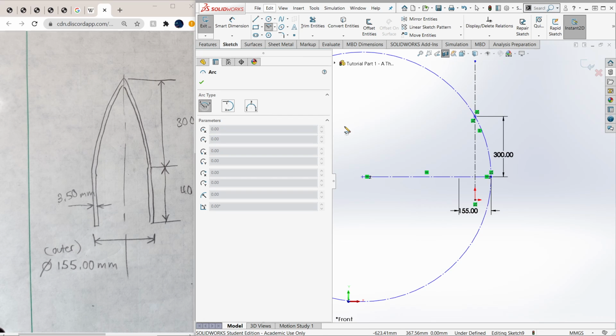So you can do it by clicking a center point, a point on the radius, and another point. You can also do 2 points. I'm going to do that one. I think that'll work. Click on this first point. Okay, didn't like that, so I'm not going to do that. I can do this other way where you define 3 points on the curve.